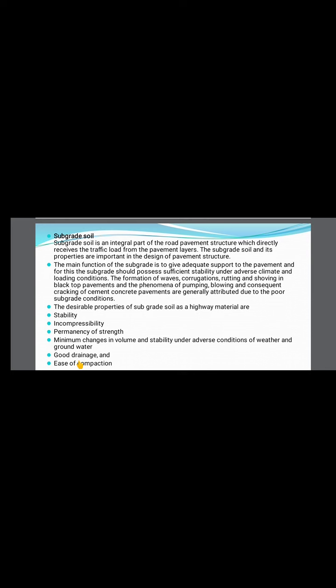So whatever different kinds of failures our roads are getting, that is waves, corrugations, rutting, showing of black top pavements, and the phenomena of pumping, blowing, and cracking of cement concrete pavements, these mainly depend upon the subgrade condition, or poor subgrade conditions. So we need to have a good subgrade, so that we can maintain a proper pavement here.